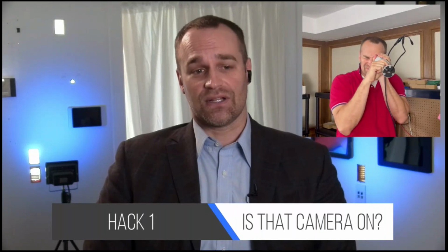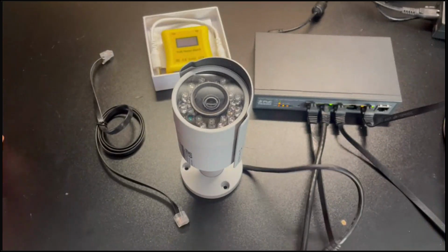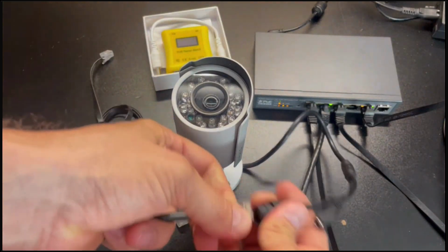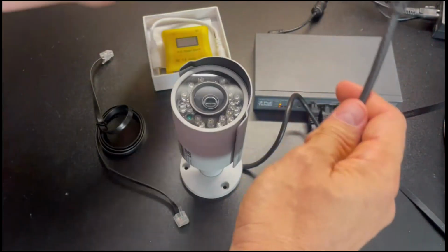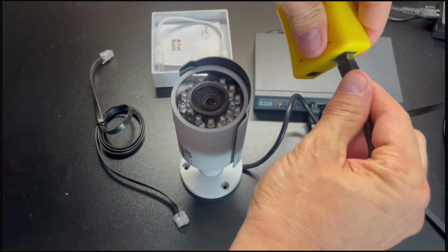Security cameras do a great job hiding their status, to the point that many of them really don't show you whether they're powered on or not. Unless there's some LED indicator light, the only ways I know to check whether a camera's on is by doing this, which should turn on the night vision and makes me look like an idiot, or by throwing a PoE tester into the circuit like this and see the camera is starting to draw power.